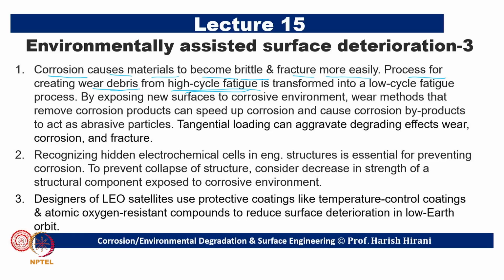So, it is more like a high cycle fatigue phenomenon. With corrosion, it converts this process to low cycle fatigue. Maybe after 100 cycles wear debris will come out, or 1000 cycles. So, that is something like a low cycle fatigue process. It is more like a multiplication factor.